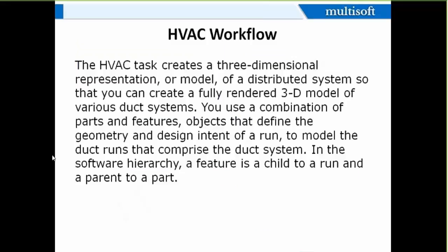Similar to piping and electrical, HVAC. In the same way you can create your HVAC ducts with rectangular cross section, circular cross section, oval cross section, and you can split the ducts. You can insert some inline components. You can insert some features as per the project requirement.